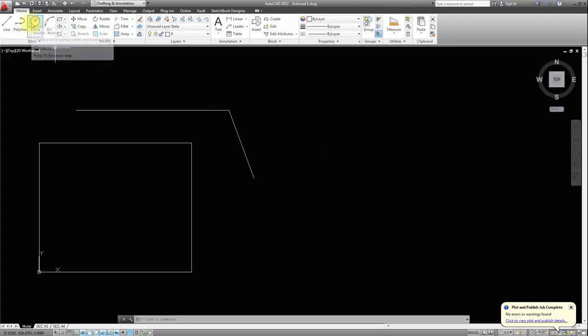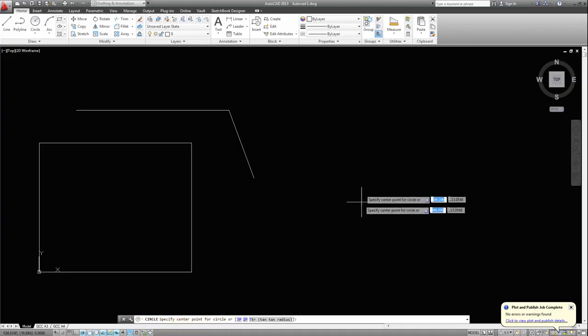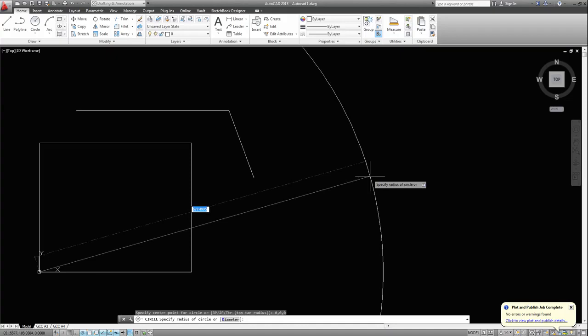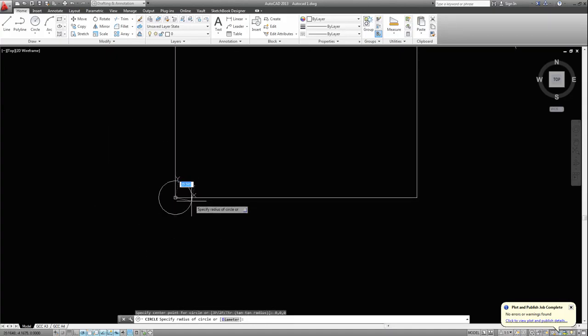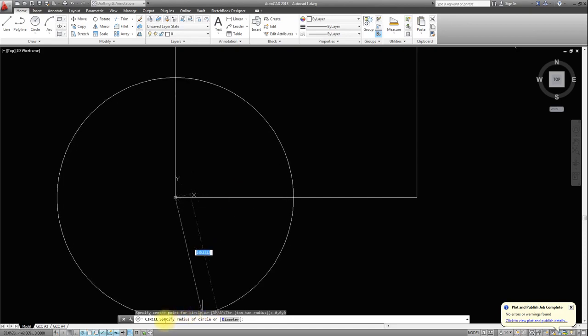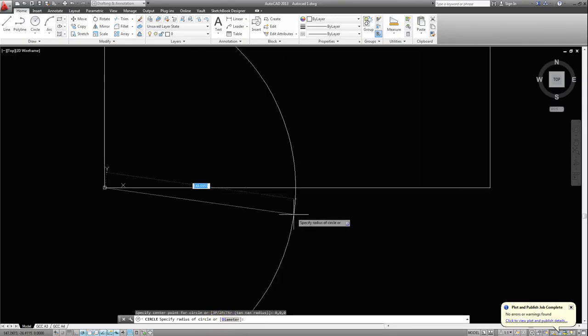Now with our circles, once again down our command bar, it says circle. Specify center point for circle. If I want to make it right on X, Y, Z, 0, 0, 0, enter. Once again, I'm right on 0. And then you'll see down on the toolbar it says circle, specify radius of circle or diameter. And you'll see diameter, the first letter, the capital letter, is highlighted.